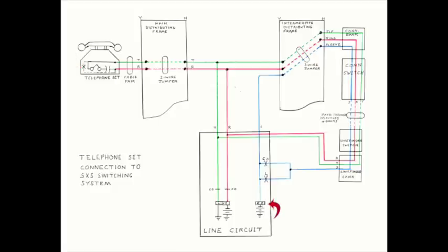The cutoff relay operates both on originating and incoming calls. On originating calls, the cutoff relay operates when the dial tone request has been successfully completed. This action opens its break contacts and releases the line relay. This stops it from continuing its request for a dial tone connection. It also makes the line appear busy to incoming calls by passing its originating connection sleeve ground through to the sleeve lead to the connector bank terminal. On incoming calls, the cutoff relay operates to prevent the line relay from operating when the incoming call is answered. This prevents a dial tone request from being initiated.